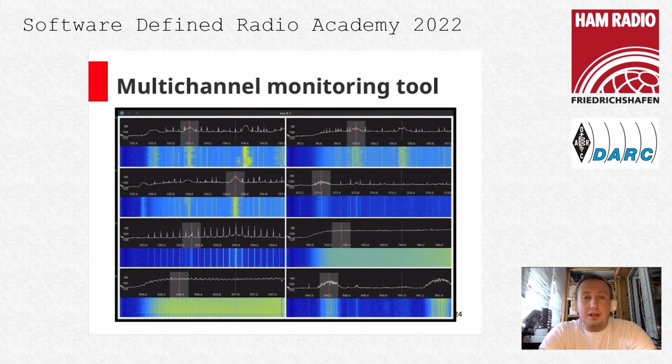In my experiments, I used this tool to monitor Starlink user terminal transmission, because Starlink uses 8 channels for upload. It's in the Ka band. So I used my whole setup, including the low noise block, LNB controller, and so on. Using this tool, I am able to see the channel distribution that the user terminal is using. So yeah, this is great and fun.